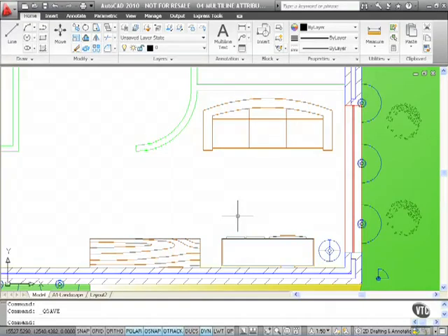We're going to look now at multi-line attributes. What this allows me to do is create attributes of multiple lines for blocks. I'm going to create a block that is a non-graphic block, just using lines of text. I'm going to set it up using the attributes setting in AutoCAD, save it as a block, and then show you how those attributes can be edited as multi-lines.